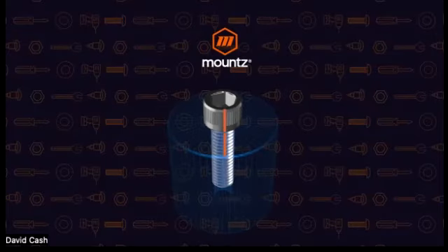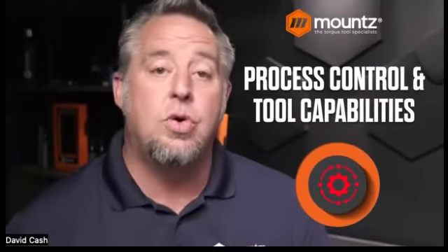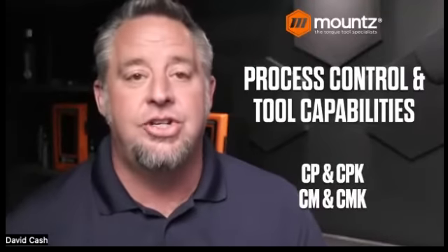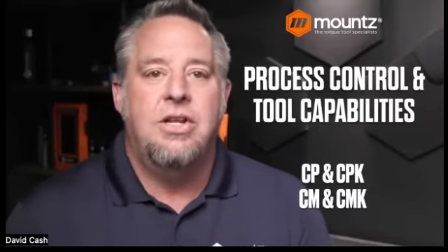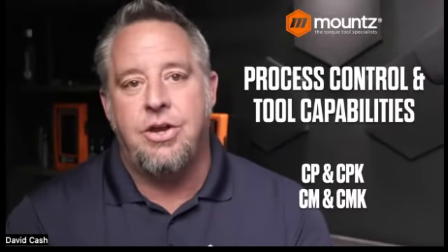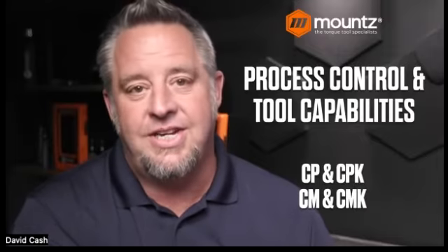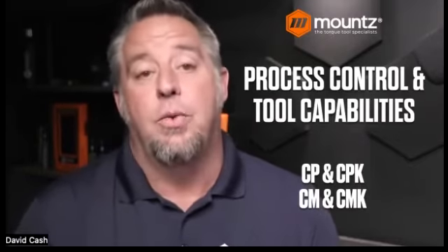And so in any event, you would need to develop those uncertainties. You can do that by capturing the data during the assembly process and also during the auditing process. That brings us to the process control and tool capabilities portion of what we're talking about, and that will lead us into the discussion of CP, CPK, and also CM and CMK. When we look at the difference between CP and CM, CP is looking at your entire process, the process that you have in place. And then the CM and CMK deals with the actual machine, or in this case, the tool that we're using.